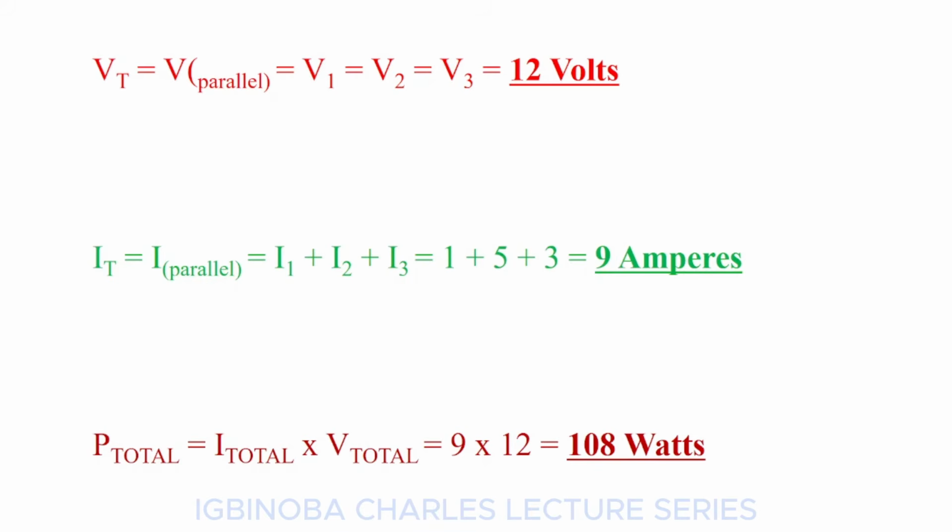When the positive and negative terminals are shorted, this short circuit current is the maximum current that a panel is capable of producing when the voltage across it is 0. That is to say, when there is no load connected to the system. That is, your V is equal to 0.